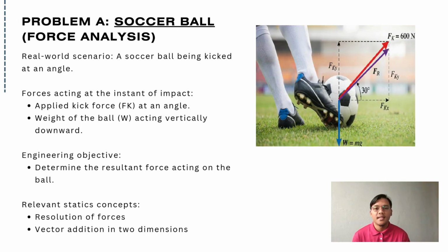Application of engineering statics in real world problems for the course BDA 10203. Moving on to our focus study, problem A, the soccer ball, which focuses on force analysis. In this real scenario, we analyze a soccer ball being kicked at a specific angle. The forces acting at the instant of impact include the applied kick force and the weight of the ball acting vertically downward. Our engineering objective here is to determine the resultant force acting on the ball using resolution of forces and vector addition.